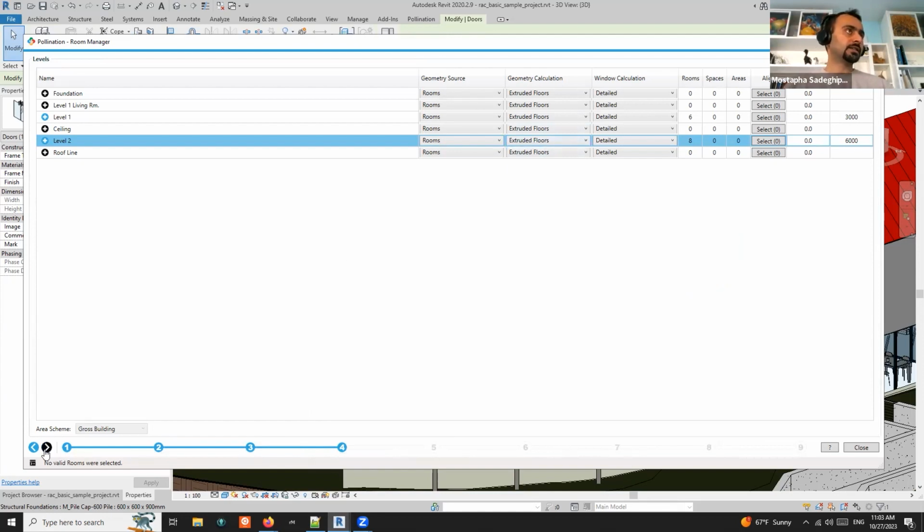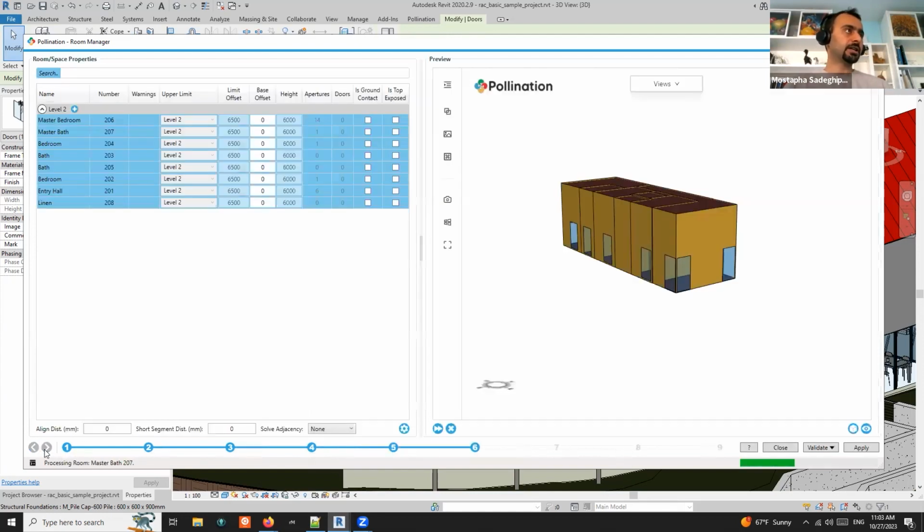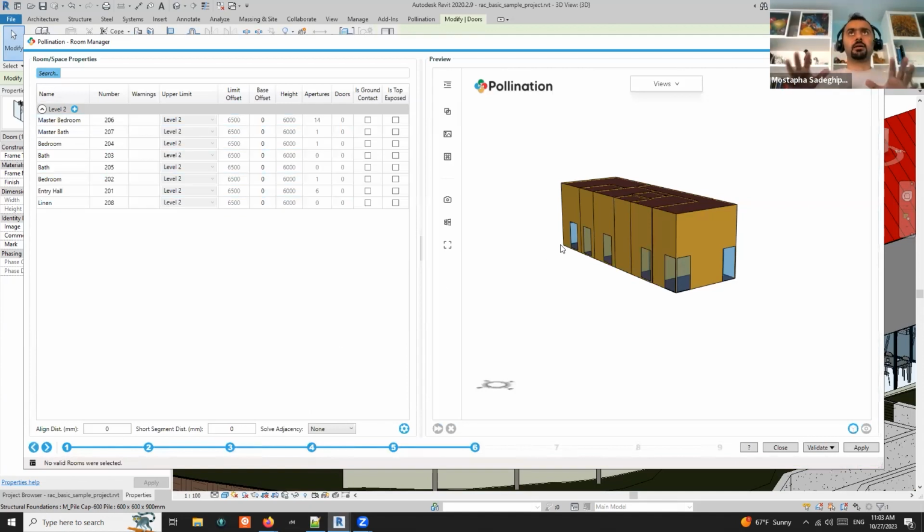Because there are cases, and I have helped several cases like this, where if you want to get that full volume thing to really work, you have to spend hours making sure all the room bounding ceilings are removed, making sure the roofs are correct in Revit, which usually is not. In this model, it's easy, we'll fix it.